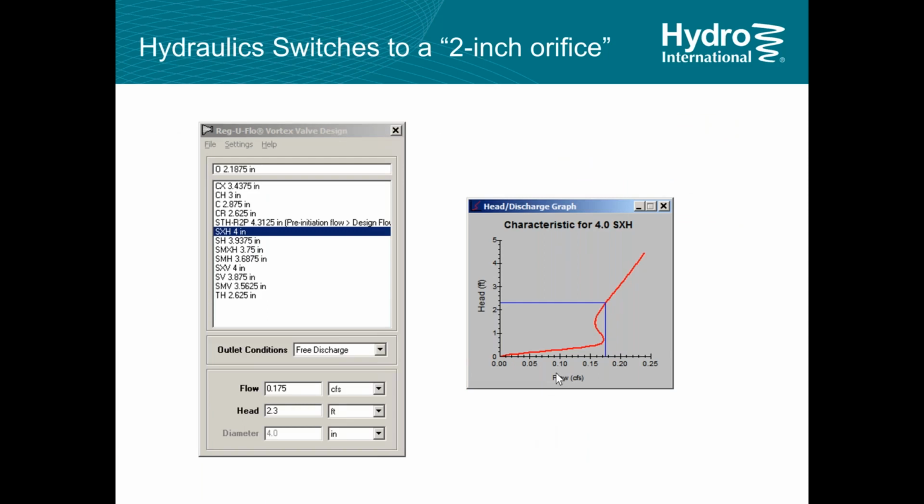It all comes down to this kind of strange hydraulic curve that vortex flow controls have. As the flow rate increases, it is letting out flow and not using the storage at all until it gets to just this design point of 0.18 CFS. And then at that point, it stops acting like a 4-inch orifice and it starts acting like a 2-inch orifice. Physically, it doesn't change. It's only hydraulically acting like a 2-inch orifice. So that soda can still pass through, but the flow rate reduces.